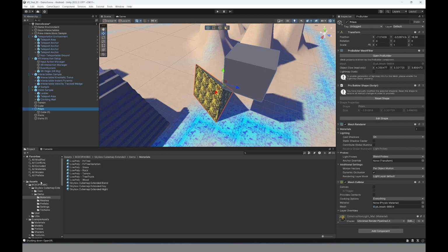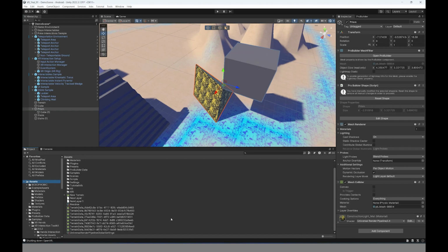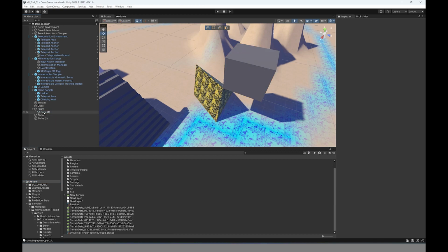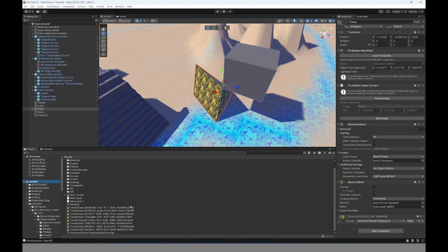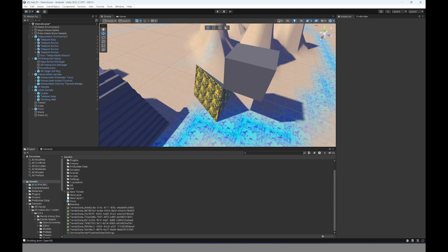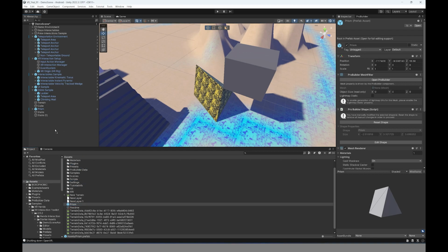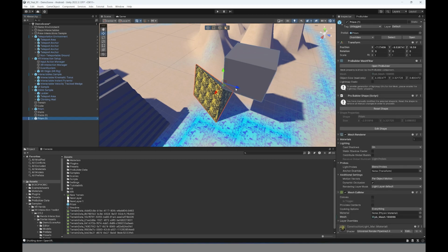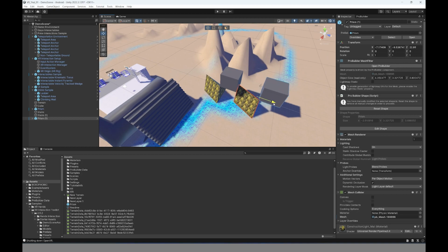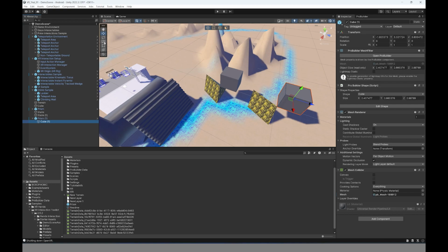But the basic gist of it is, let's say I'm in assets, and if I simply want to create a repeatable version of this prism and cube, I can take my prism and I can drag and drop it in my assets, and you'll see how it creates this prefab looking thing here. So if I take this and now drag it and drop it back in my hierarchy, it'll give me another assembly or prefab. And then within here, I could select my cube, for example, and I could make changes to it separately.